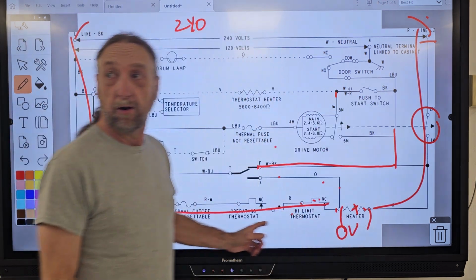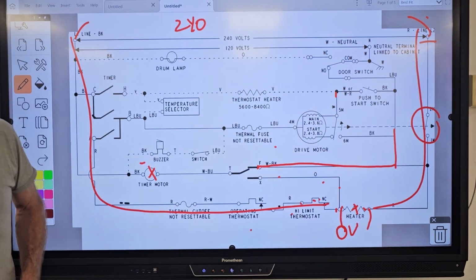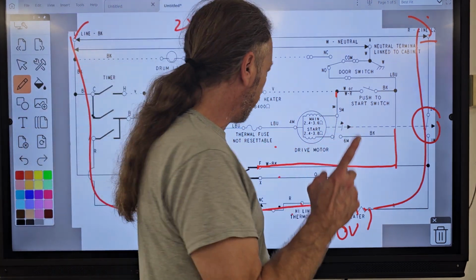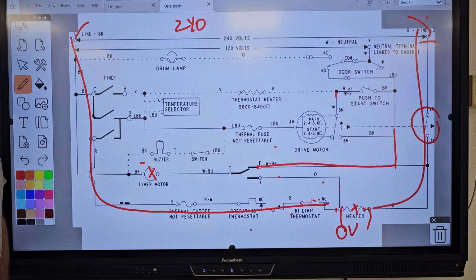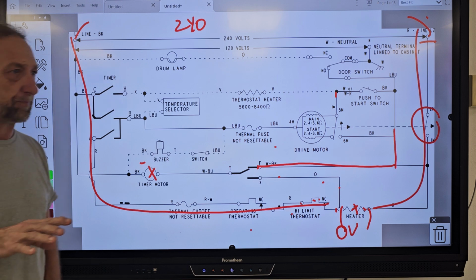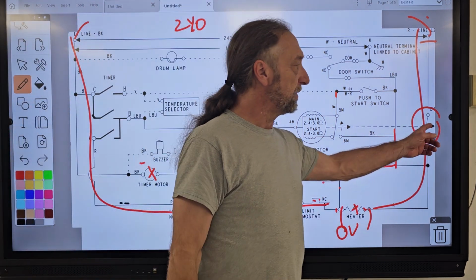I'll go right first because it could be the shortest distance. I'll go towards the shortest distance, get that, knock that out. Well, no, if you mean the switch, the switch is going to be up top behind the thing. Everything else is going to be closer to your left. The switch you're talking about is the centrifugal switch, right? You'd have to check underneath, on the motor.